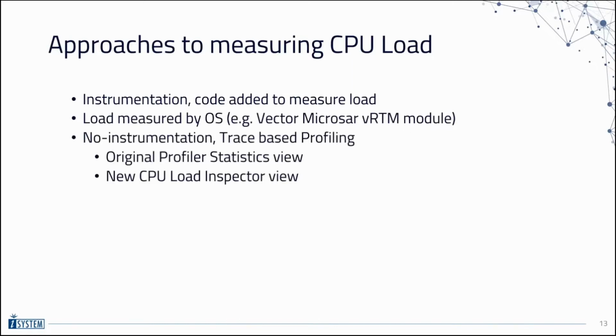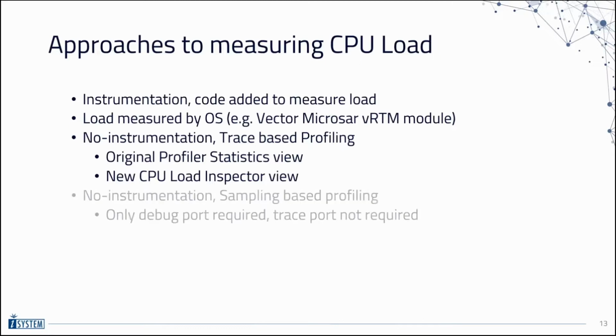Next we have the no-instrumentation trace-based profiling. This is what you can do in WinIdea if you have access to a hardware trace port on your target, like a Nexus or ETM or Aurora. Later in the demo I'll show our analyzer and the profiler statistics and the new CPU load inspector. Finally, I'll show our no-instrumentation sample-based profiling, which only requires a debug port. No trace port is required.